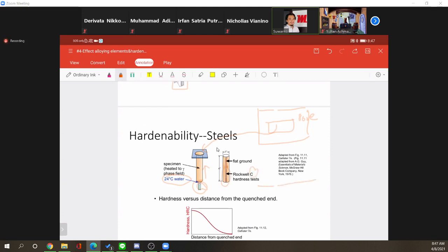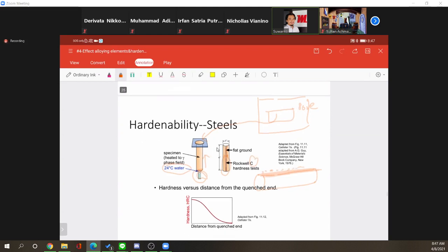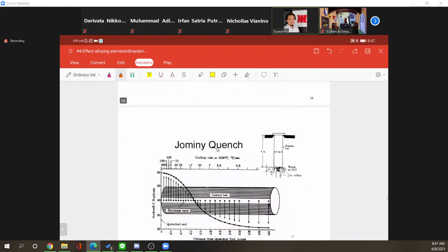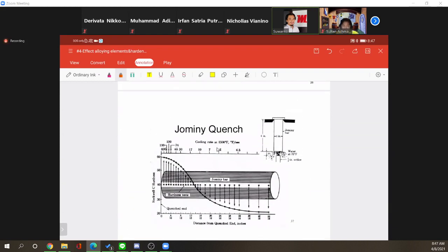So you have something like that. This is your sample. You scrub it and measure at each position. Maybe you will have a hardness laboratory work, like on the metal one, so you know how to measure it. You measure here one by one, at every point, and then make a plot. So you measure on the surface, one by one, at a distance of about 1/16 inch.